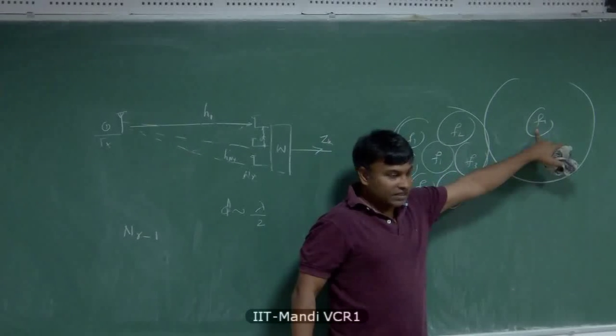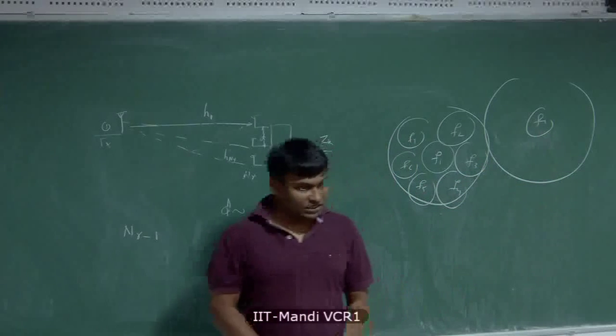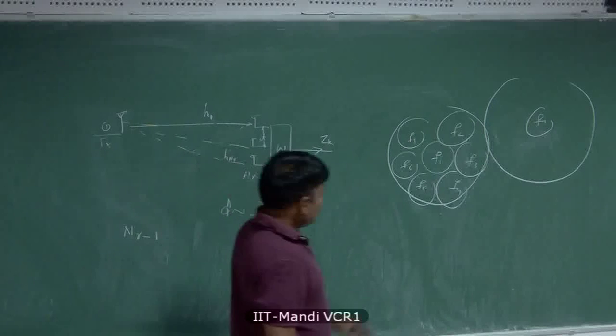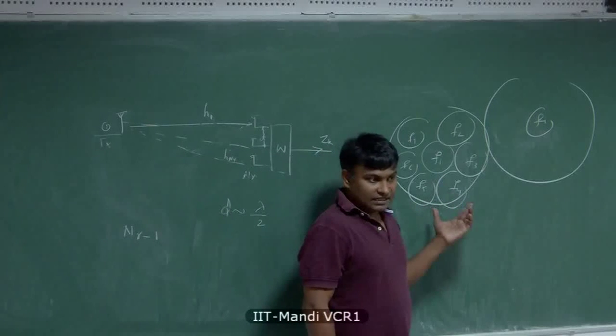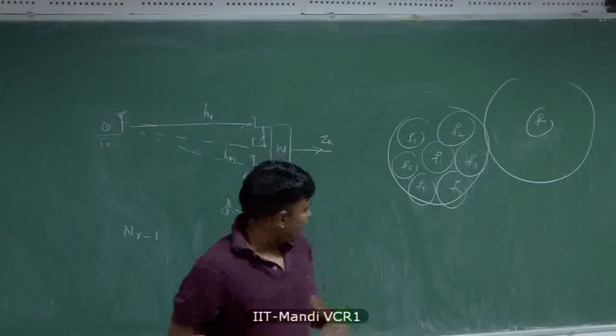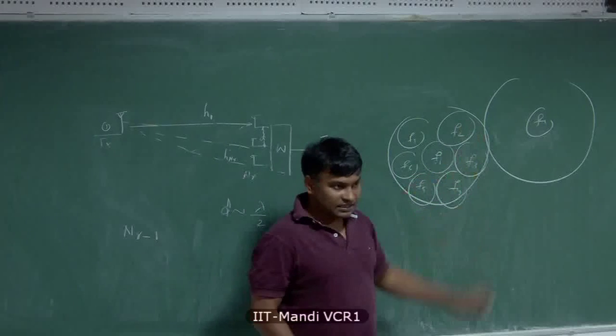the first dominant interferer will be coming from a large distance, therefore the strength of the signal is low. That is one way of designing cell sites. In the early systems, that's how GSM systems were designed. This carrier is not reused in the adjacent cell site.